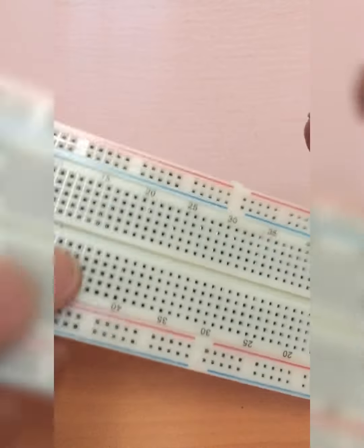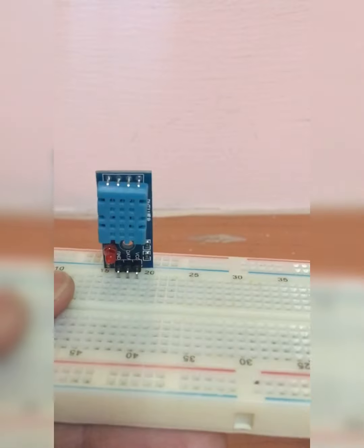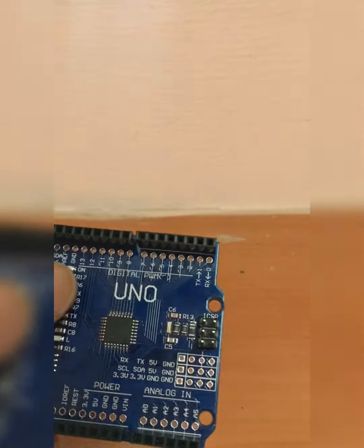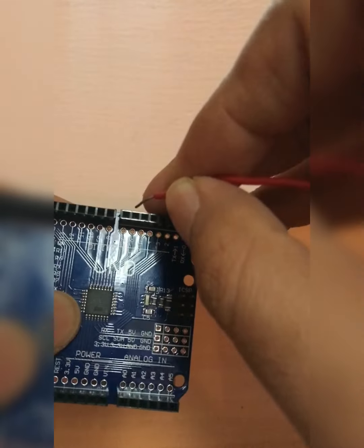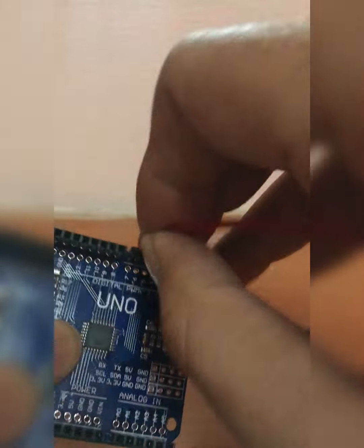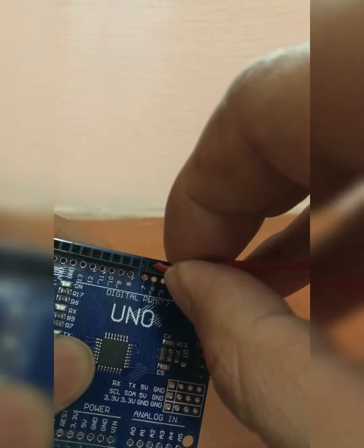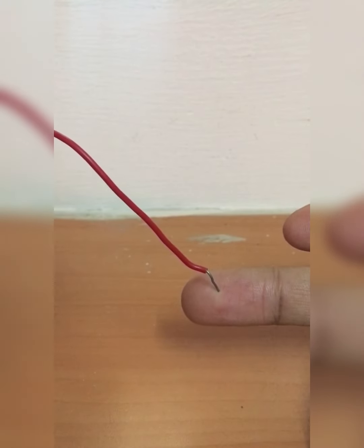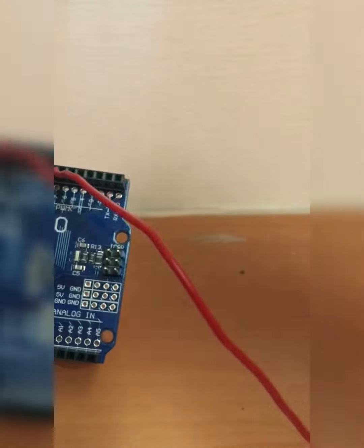So first, I will take the breadboard here and I will insert this DHT11 sensor like this. I have inserted it, and take this Arduino Uno, take 3 single strand wires. I will take the 7th digital input pin and take one point to the 7th pin, and this point is to be connected to the data input pin of DHT11 sensor, and take one more wire from